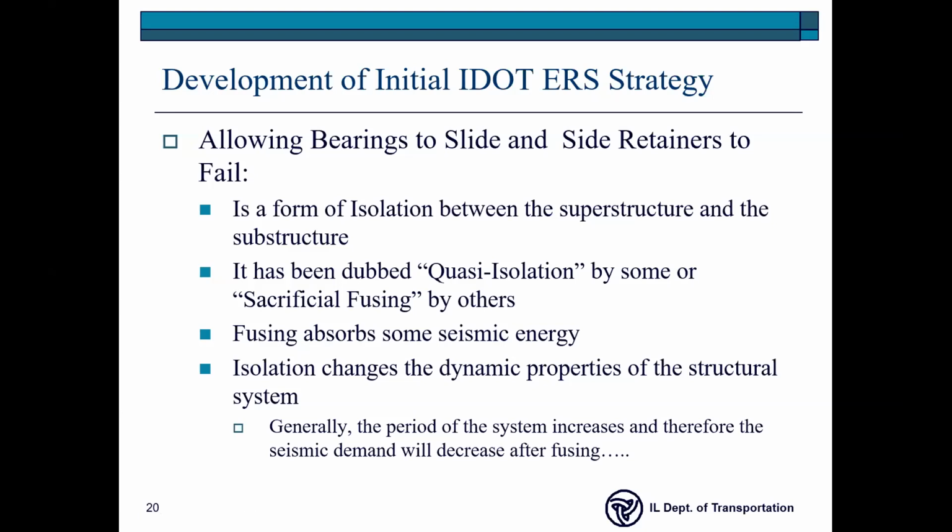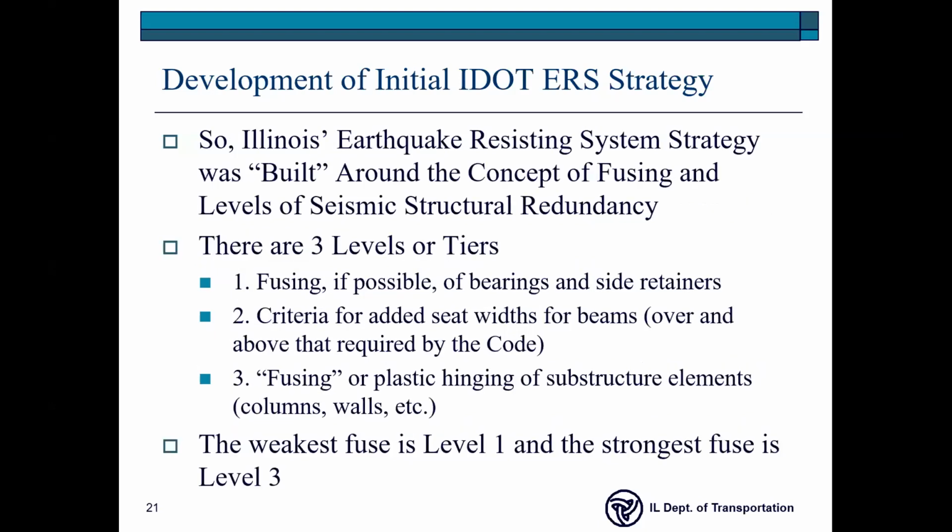It lengthens the period. And if you don't know very much about structural dynamics and earthquake engineering, if the period of your structure goes up, that means that the response of your structure will be less. Okay, and you have to know a lot about structural dynamics and earthquake engineering to fully understand that. So our earthquake resisting system strategy was built around this concept of fusing and levels of what I call